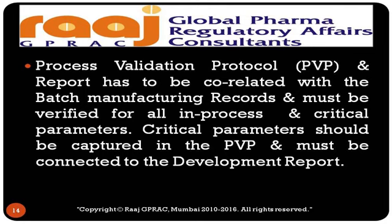Then the process validation protocol and report have to be correlated with the batch manufacturing records and must be verified for all in-process and critical parameters. Critical parameters should be captured in the process validation protocol and must be connected to the development report. For each product you must be aware that process validation plays an important role, and you have to take a minimum of 3 batches for process validation, because of the consistent result, right? Once you get the consistent result, then you can claim that your process is validated.